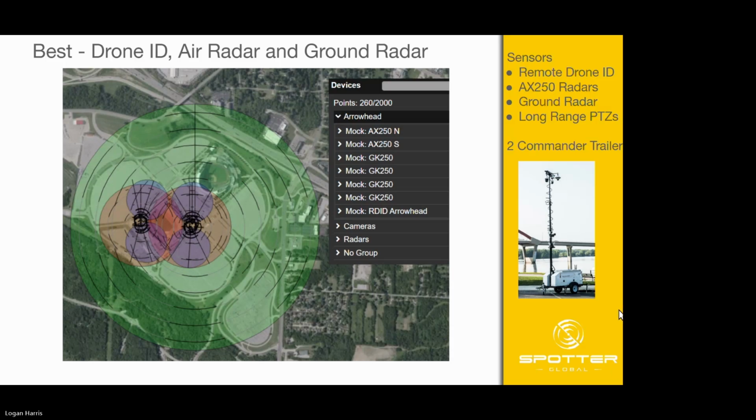So the remote ID, that's what I'm showing here in the big green circle. This green circle is 750 meters. That's where you want to be to do real-time camera cueing. Outside of that, you can still track, you can still detect out to a 3 kilometer radius.